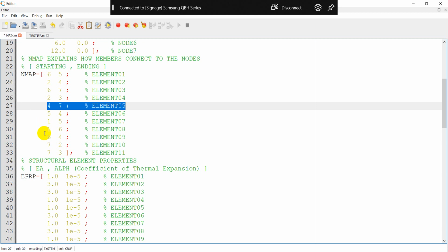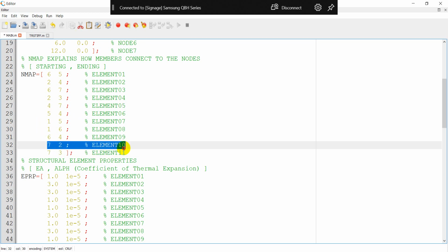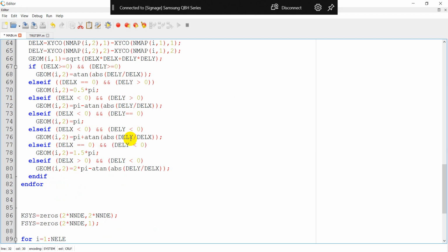Or the case like this is a case that we generally don't like. You have the larger node number there for the starting node, and the ending node goes with the smaller number. So that means the first 2 columns and rows are 13, 14, and then you come back to 3, 4, right? It switches around. But it doesn't really matter. The computer just takes care of this. Or when you do hand calculation, you just follow this, just drop in the entries to the right destination. That's the whole idea.